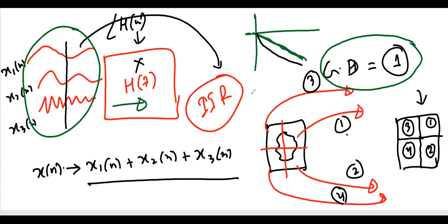That is where the all pass filter comes in. It has an excellent characteristic by which we can control the nonlinear phase toward linear phase to some extent, not exactly for all conditions, but we can control the IIR filter nonlinearity toward a linear filter.